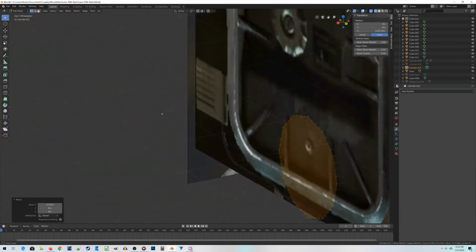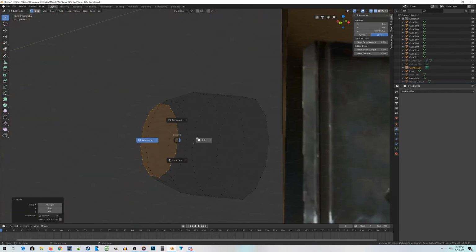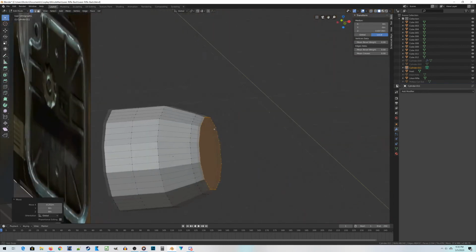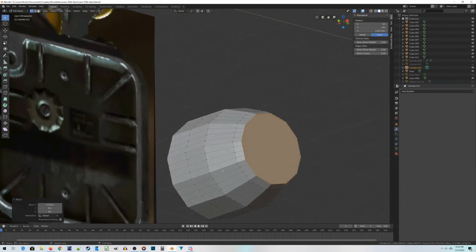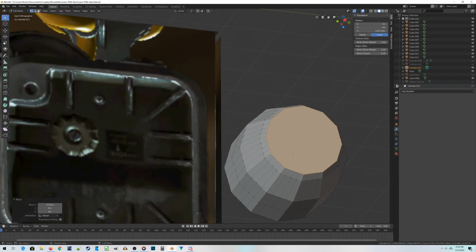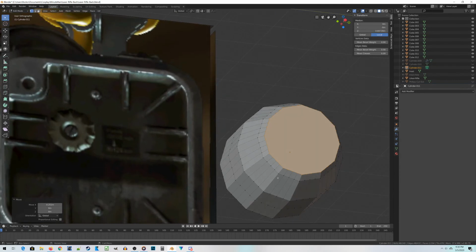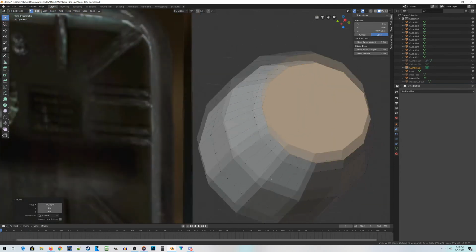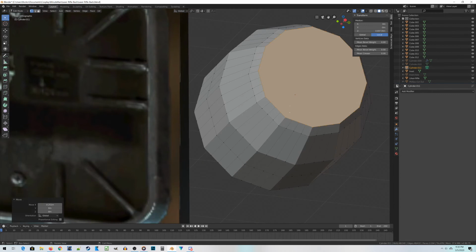Move it close to the top like that. Okay, so now this is where you get into some of the weird mesh manipulations. Because how we're going to make these little ridges is that around each of the major edges of our 12-sided polygon, these two sets of faces right here are going to correspond to one of those ridges. So we need to start by deleting the faces that are on the inside.